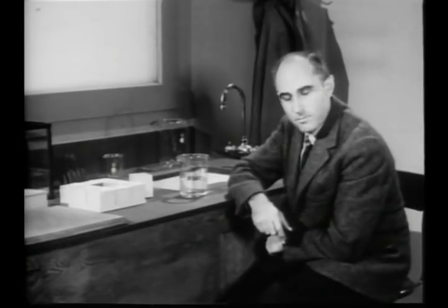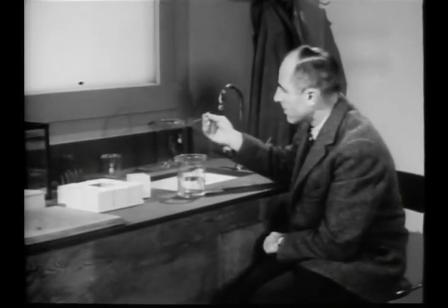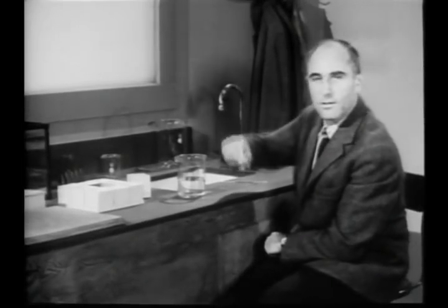It is continuous, and it has certain average properties which represent the statistical behavior of the countless molecules of the real fluid. One such property is the density. Let us think of a very small lump of fluid, smaller even than this droplet, which nevertheless contains many molecules. The average density is defined as the total mass of all the molecules of the lump to the total volume of all the molecules with their surrounding space. Density is mass divided by volume.